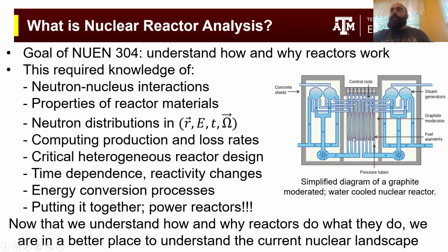So the coolant comes up, it goes through the core. This coolant is cold when it goes into the core. As it passes through the core, the fuel transfers heat to this working fluid. And so as the fluid goes up through the core, it heats up, its temperature changes, its pressure changes, and ultimately, depending on the design, that hot fluid is then either taken to a heat exchanger, or in this design, this is a boiling water reactor, which means that as the coolant goes through the reactor, it actually starts boiling while it's in the reactor, and you have a steam generator that is basically a part of the primary circuit here.